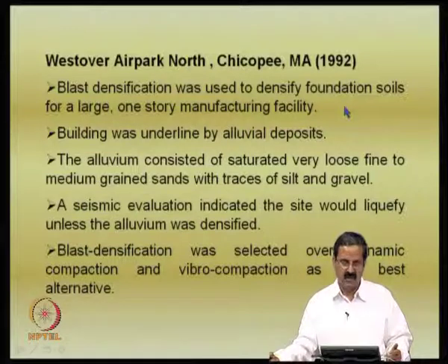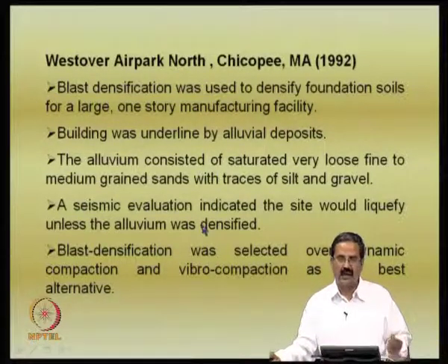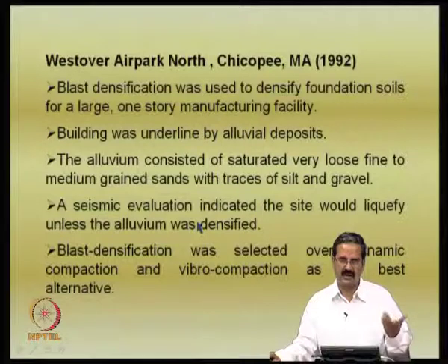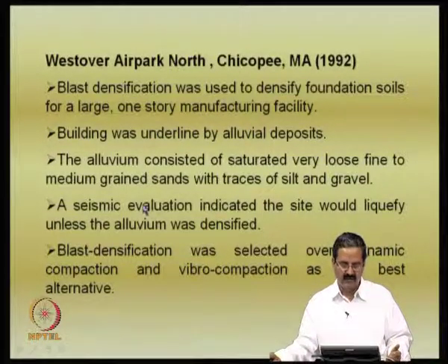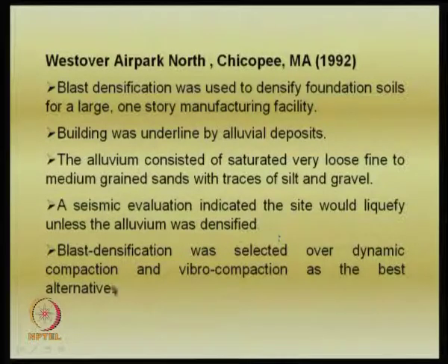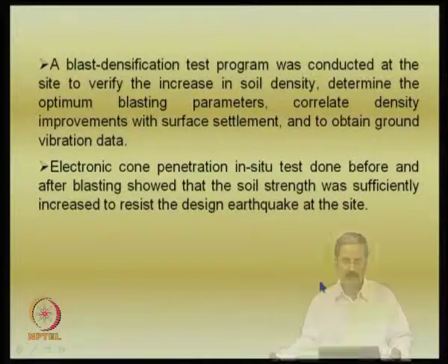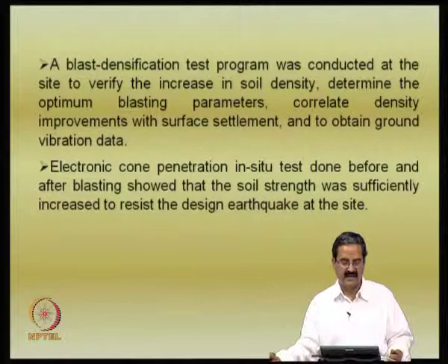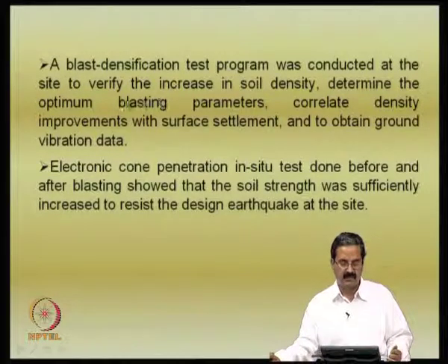That is the inference. So, the seismic analysis was done, they arrived at the design earthquake motion, and when they verified the design, they found that it could lead to liquefaction. So, blast densification was selected over dynamic compaction and vibro compaction as the best alternative. As I just mentioned, this was found to be economical. A blast densification program was conducted at the site to verify the increase in soil density, determine the optimum blasting parameters, correlate density improvements with surface settlement, and obtain ground vibration data.